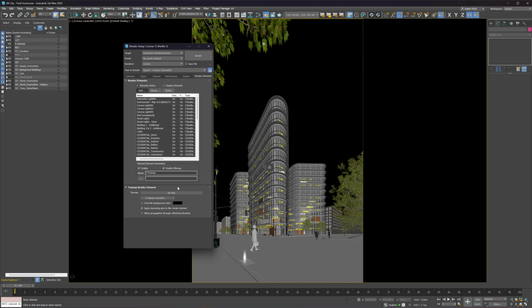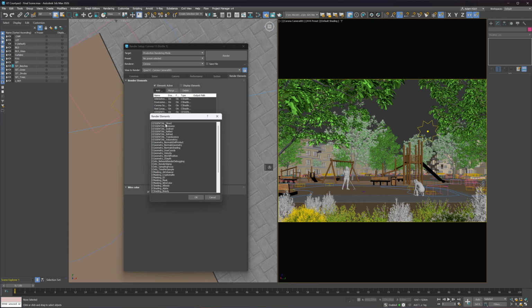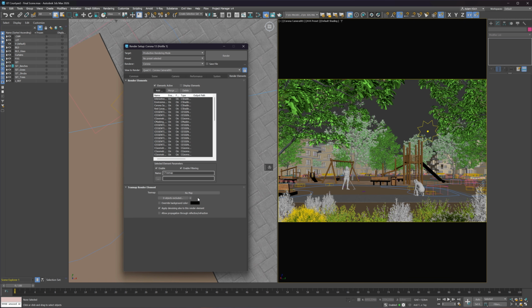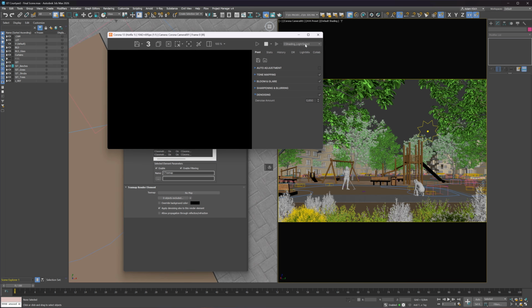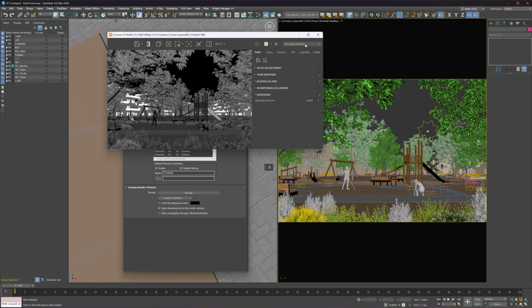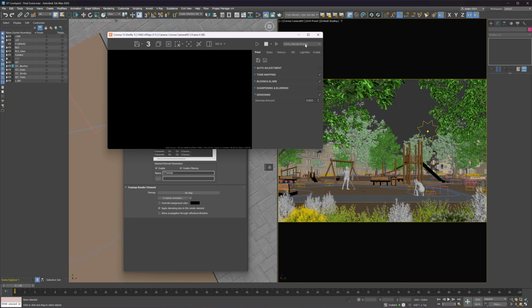And even when they don't multiply the render time directly, they can make your render heavier, bigger, and the workflow slower. The common mistake is turning on every possible pass, because maybe you will need it later. You probably don't. If you are rendering a simple still image, do you really need 20 different elements? Do you need every lighting pass, every mask, every raw component? Before rendering, ask yourself, what am I actually going to use in post?